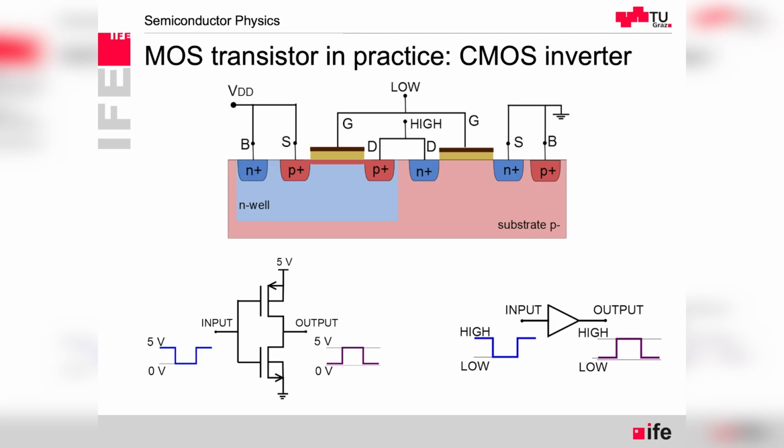So for one thing, there is the leakage current between the drain and source. That follows the subthreshold operation expression, depending on all the same as here. And we have a bulk leakage current related to the drain-bulk diode.